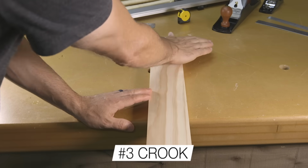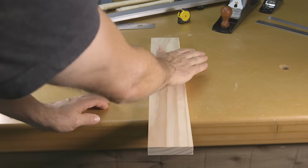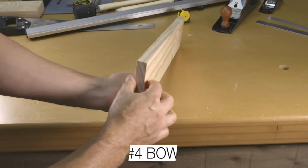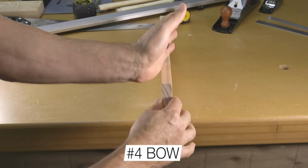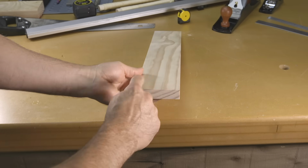Number 3 is a crook. A crook is when the board or lumber bends to the right or to the left in the direction of the edge of the material. Number 4 is a bow. A bow is similar to a crook, but this time the board bends in the direction of the face.